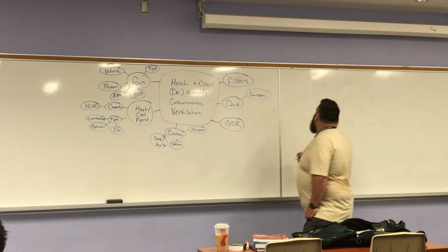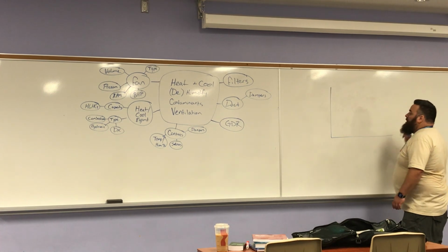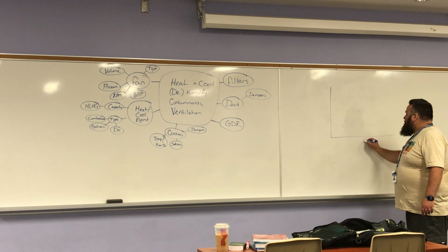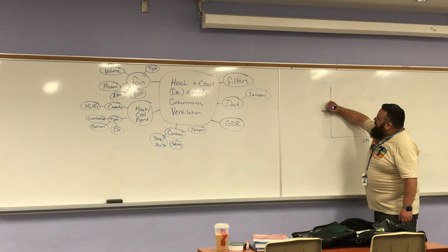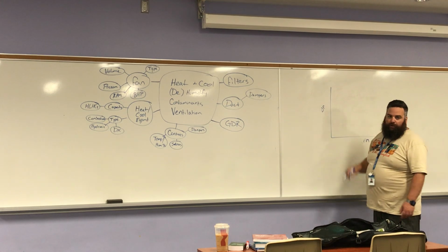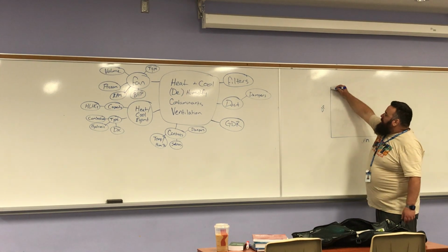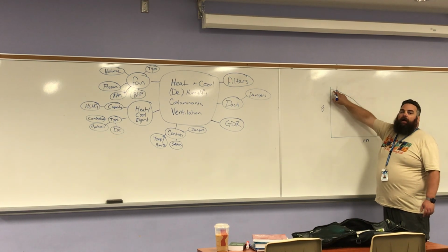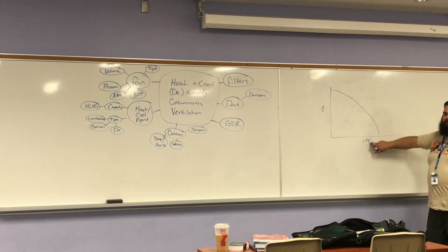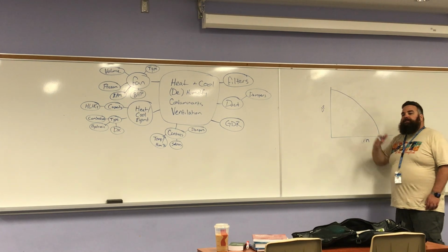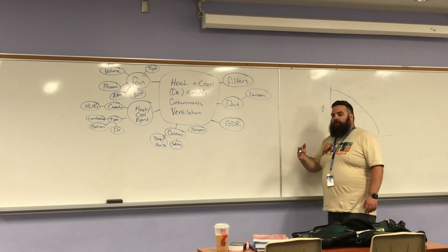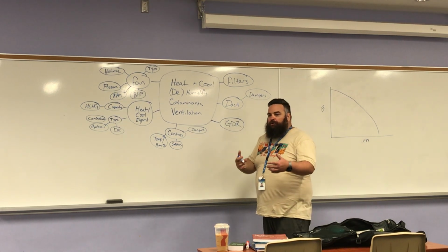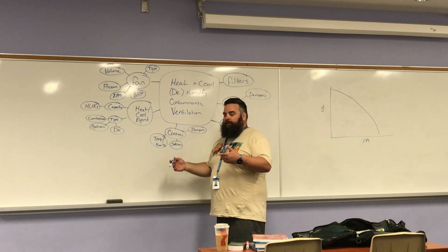Do you recall last week when I talked about the fan curve? We're going to look at that, right? So my CFM is here, and my delta P, my pressure drop, is here, right? As my pressure drop increases, the higher my pressure drop, the lower the CFM my fan moves, right? So if we want to control the CFM that flows through a duct, we can close that damper, which will create a restriction, induces a pressure drop, and now less air moves through it, okay?